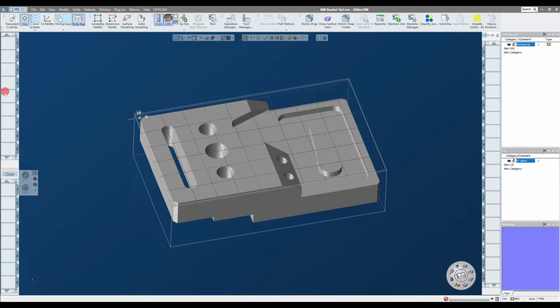Now once you create a tool, you'll move down to this lower section of tiles. Now these tiles are where your in-process processes are. So this is where you would start entering whether you want to do a contour or a pocket, a drilling operation. You would put in all of your parameters for depth of cut, all of that information, and your in-work process belongs here. Once you actually create the tool path by applying it to your model or a piece of geometry, your finished operation will end up here on the right-hand side, and this is where you'll eventually end up with a longer list of actual operations. So tool, process, operation over here on the right-hand side.